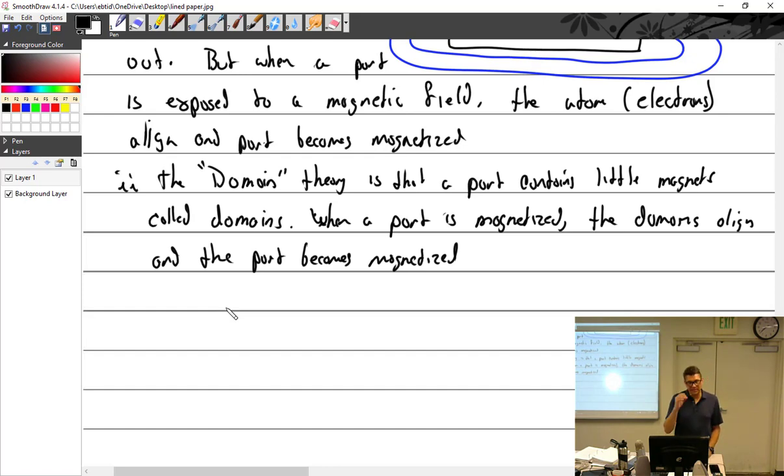But to demagnetize it, we put it in the machine, and it uses alternating current, which goes back and forth and diminishes. So it scrambles those domains and leaves them all over the place again. Once they're scrambled, you don't have the magnetism left in the part anymore. Then you're going to put it into a machine and put DC current through it. DC current only goes one way, and it will magnetize the part back to normal.